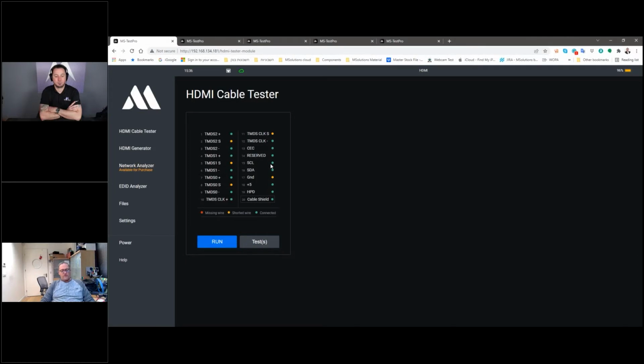And by the way, when we're talking about HDBaseT, for example, most of the time from our experience, the failures are not coming from the HDBaseT itself. It comes from the HDMI on both ends. If you have from the source to the HDBaseT transmitter an HDMI cable that brings the signal with a certain level of error rate on the HDMI, the HDBaseT will not be able to carry it. And while it transmits from transmitter to receiver, you will get video drop. So understanding your HDMI quality is very, very important.